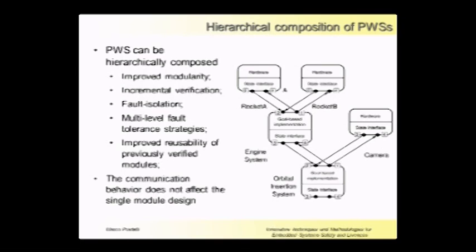This pattern and the part-of Statechart approach allow us to improve modularity, to perform an incremental verification, because the verification of each module is performed in a standalone process, and then to implement a multi-level fault-tolerant strategy, for example. And most important, the communication behavior of the whole system is not spread over all the components, but is contained in each module. So only important events are propagated along the structure of the system.